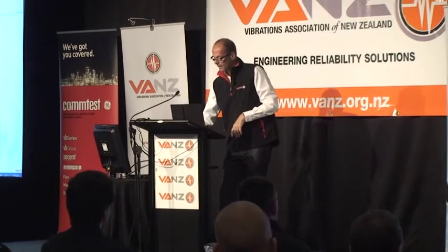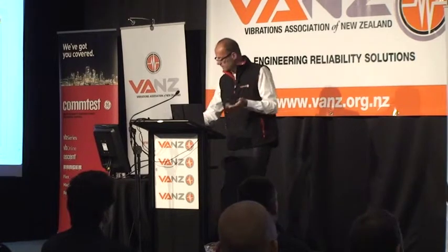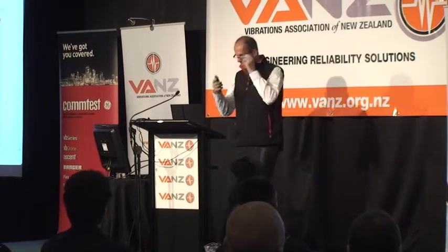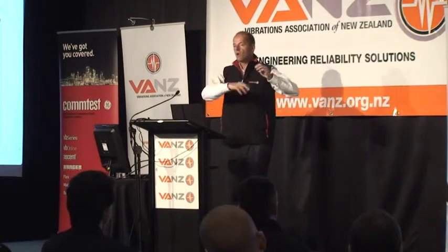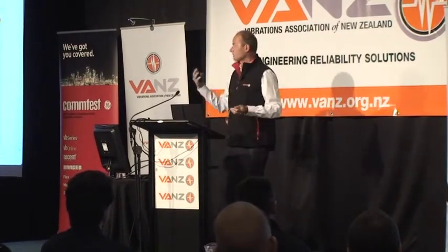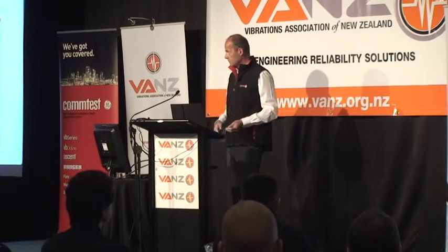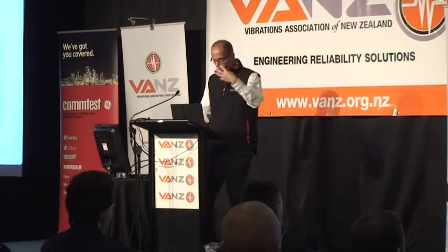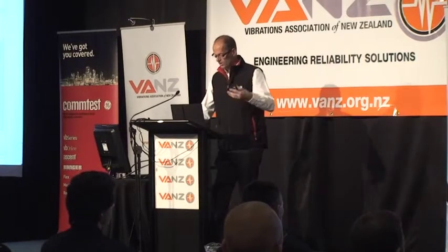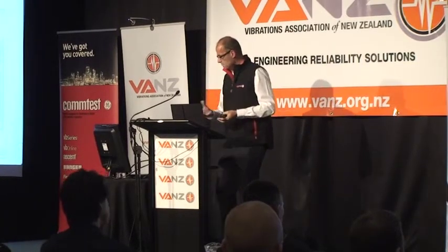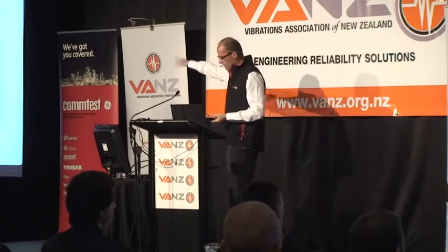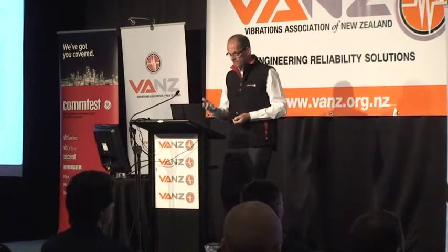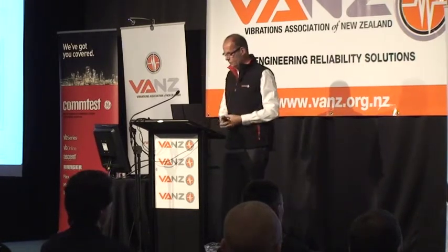Okay, so the bottom line is, we're starting from that point where we get this signal. Obviously, the time waveform can be complicated, but it can tell us an awful lot about what's happening inside the machine. The spectrum makes it simpler to understand. In really basic terms, the basis of vibration is that with that motion, we get this simple harmonic motion, this simple sine wave. As the shaft turns, it's one frequency, which we can represent as one sine wave.